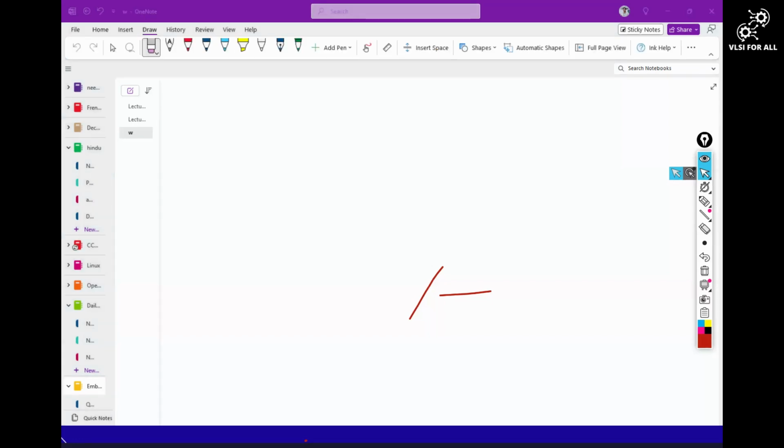So you have an Amazon Alexa, right? So this is Alexa. Now you provide your voice to it. What's happening here? You have a microphone, right? It has an ADC inside it. It is converting your analog voice data into digital data. Now it gives this digital data to the main part of this Alexa, to the processor, via a protocol called I2S, right? Now this is done.